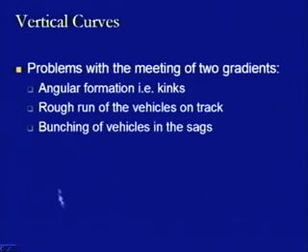All the vehicles coming towards this location, whether from the downward gradient or going up the upward gradient, have the tendency to go towards the lowest point of that trajectory. This is just because of gravity, due to which all these vehicles will try to align with respect to the sag. It means there will be an accumulation of a number of vehicles within the sag area, and this is what is known as the bunching of the vehicles.